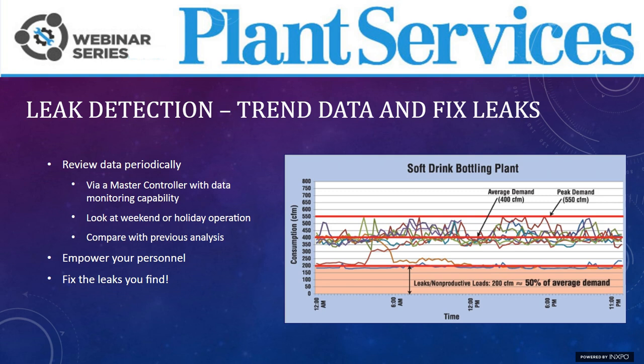As Timothy showed us, trending data can be easy to do, but it may not be easy to analyze. A quick tip would be, if you have this kind of data, pull up your flow values for the weekend or holiday operation. Check what percentage of your flow is running during this period, and then trend that information. Has it gone up or down? If the change is significant, address it immediately, either with another leak audit to find and fix those leaks, or maybe with a company-wide announcement on how much you've reduced your leaks. There's plenty of incentive to empower your personnel.